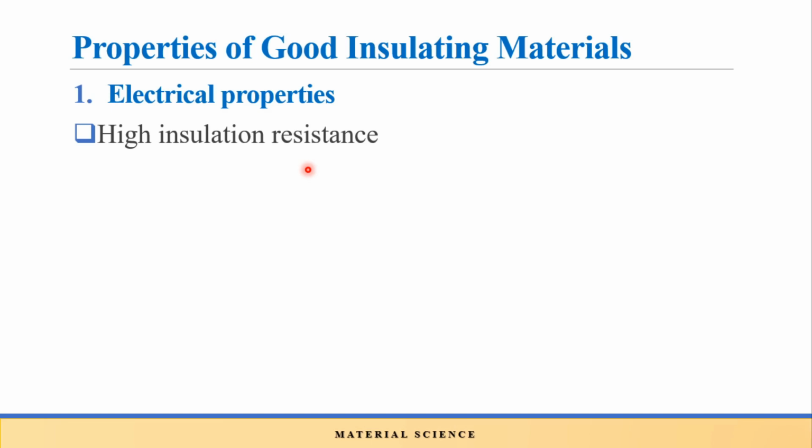What is insulation resistance? It is opposition to flow of leakage current, and we know that in case of a particular cable, insulation resistance decreases with increase in temperature. If temperature is increasing, then obviously the insulating material will lose its insulating property somehow, not all, but somehow, and insulation resistance will get reduced.